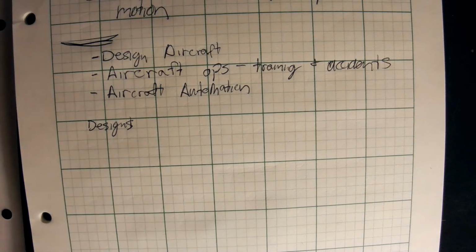First we have the aircraft designs. What I mean by that is what they actually designed the aircraft for. Key things they keep in mind are stability, and more specifically the roll stability. By law, aircraft are required to be able to take off without all their engines. So for a two engine aircraft, they have to be able to take off with just a single engine, and they have to be able to account for it. Because if one of the engines blows out, you're going to have a huge moment force trying to spin it around. So they have to have big enough control surfaces on the back in order to counteract that moment force.